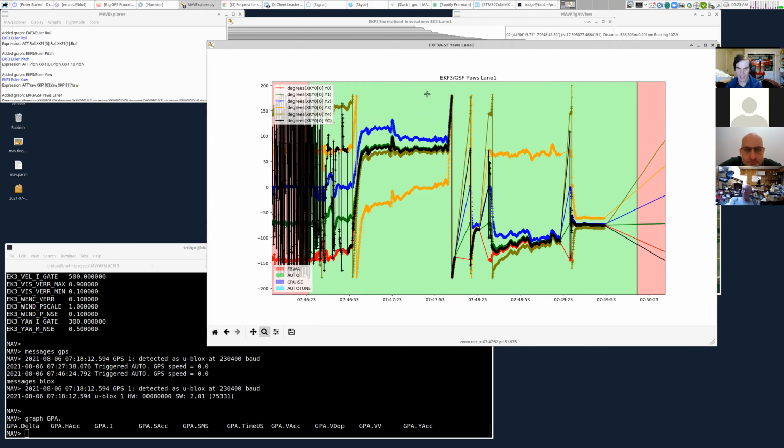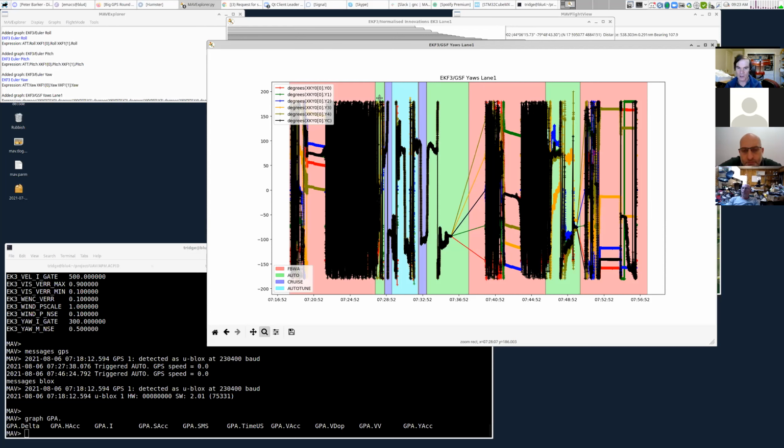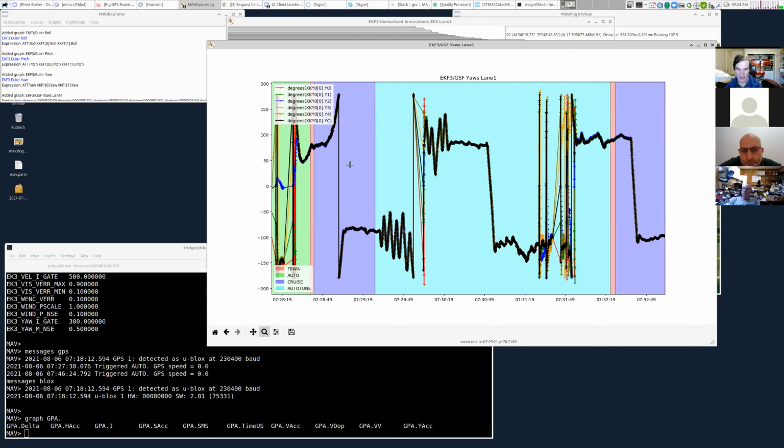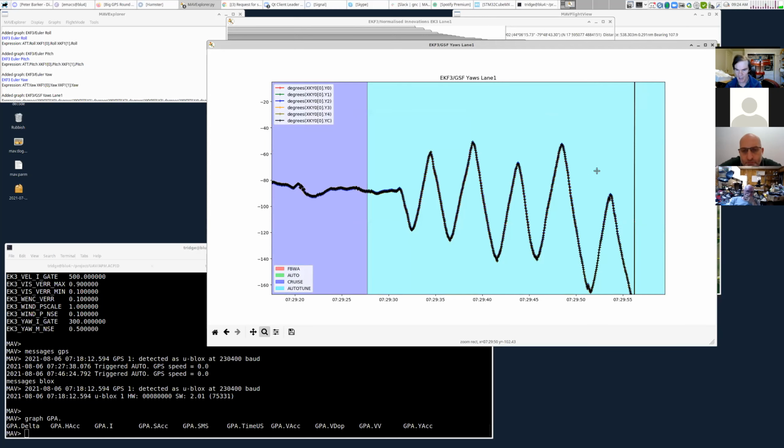So what we see is several different yaw estimates, which at this stage of the flight then converge on the one estimate here, but then he reboots and goes again. This is a yaw estimate that is based on the correlation between the IMU and the GPS. And it's a great way of double checking whether the yaw is correct. You can see it converged here fine.